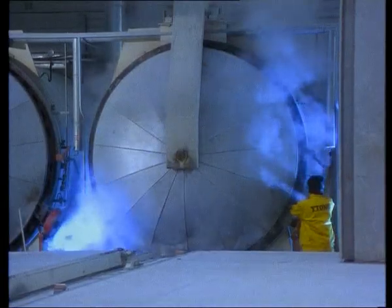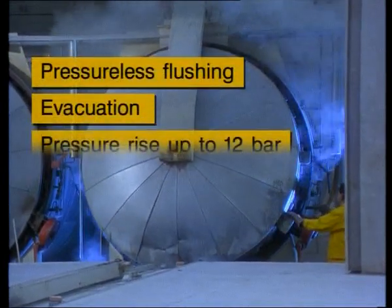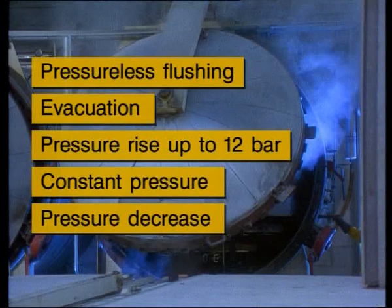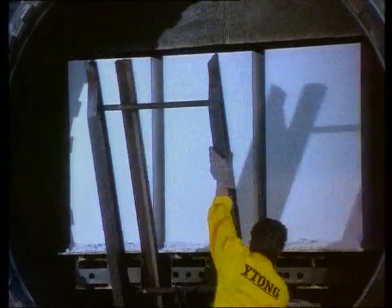The curing process is characterized by the following 5 phases: pressureless flushing, evacuation, pressure rise up to 12 bar, constant pressure phase, and pressure decrease to atmospheric pressure. The curing process normally takes 12 hours. When the curing process is terminated, the rod feeder enters the autoclaves and pulls out the train of 4 curing trucks.